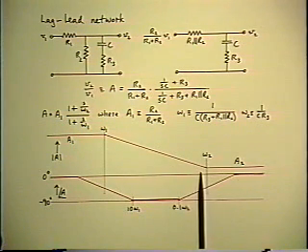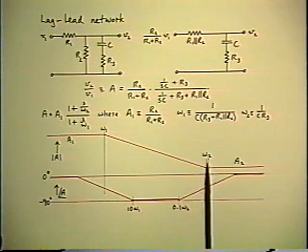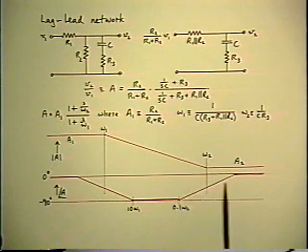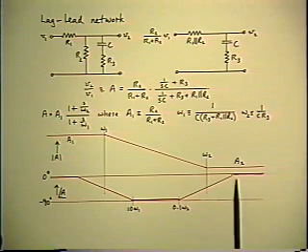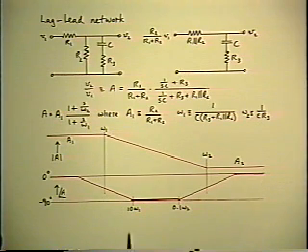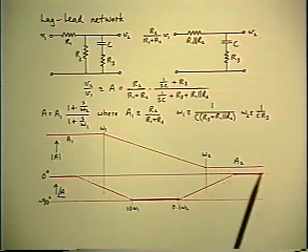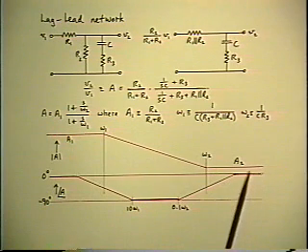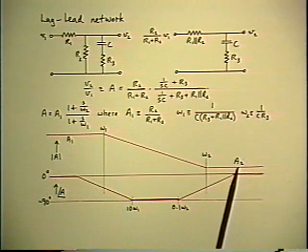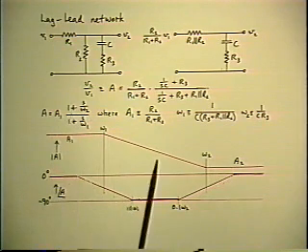Eventually, we'll arrive at the omega 2, which is the 0, so it will be a concave upwards corner and a corresponding plus 45 degree per decade phase asymptote. So that's the basic magnitude and phase configuration. Now notice that we have two flat gains, and I've labeled the other one A2, but that was the last thing that happened because A2 isn't anywhere in this formula.